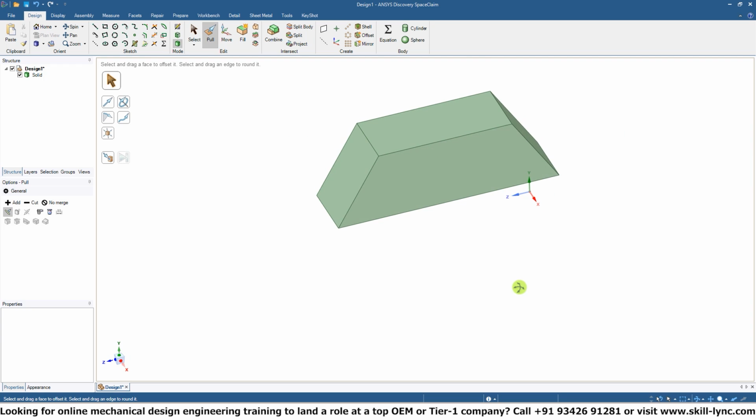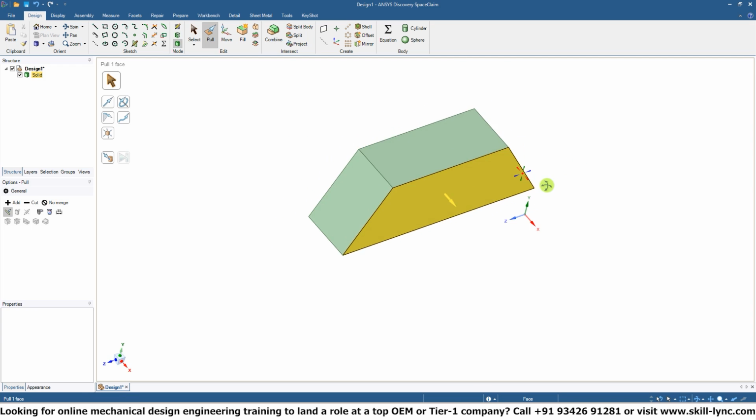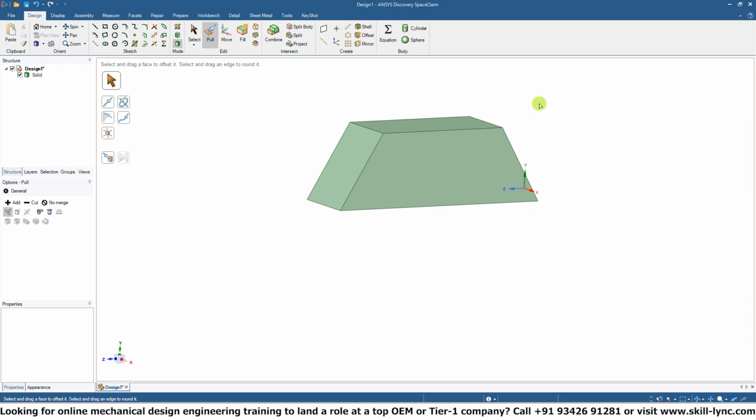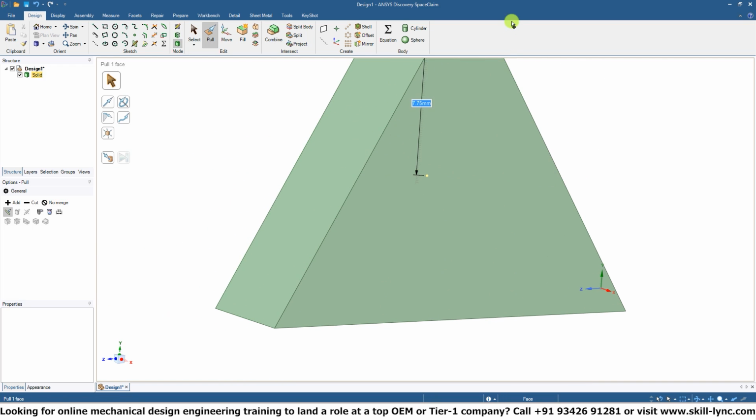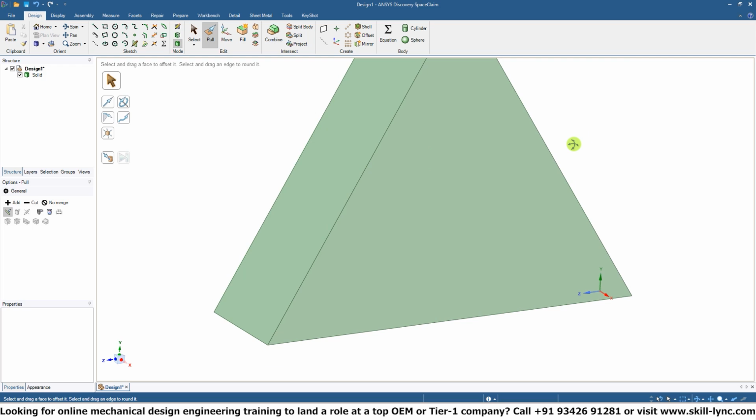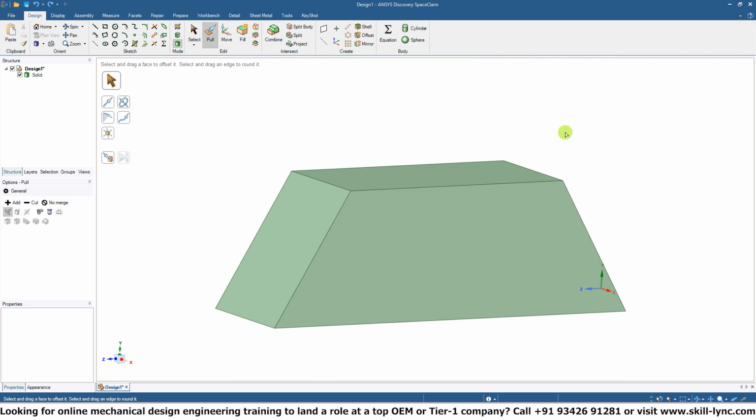It extrapolates it outwards. In this section, it can do it like this. You can see how you can quickly manipulate your drawing or your 3D geometry using this simple tool. And you can see how with one simple click and drag, you've eliminated so many of the steps where you go back into the sketch tool, you define a sketch plane, you have to sketch the exact geometry, you have to make sure it's accurate, and then go into the 3D modeling tool using the pull tool and complete the geometry that way. That's a lot of effort and it's very time consuming.